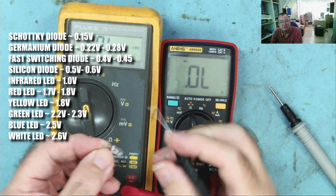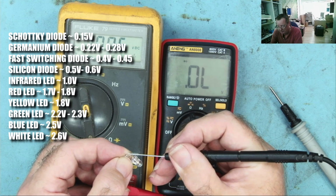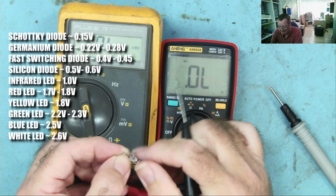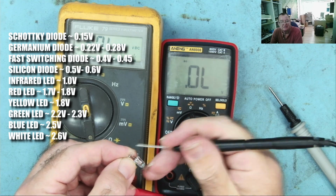I guess if we pointed my phone at it with a camera, we'll probably see it lighting up, but that is an infrared LED. We'll just measure the other way. Should read open if it's a good one. Yes, it reads open.